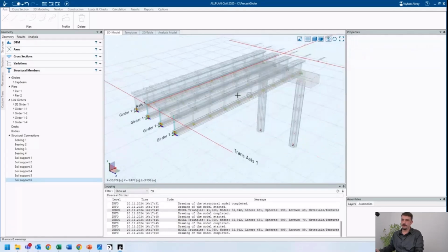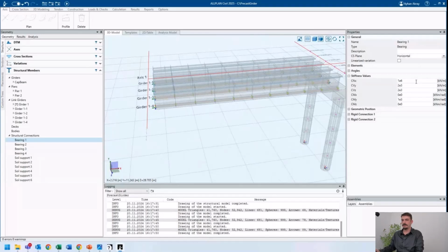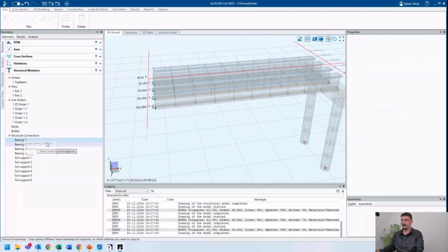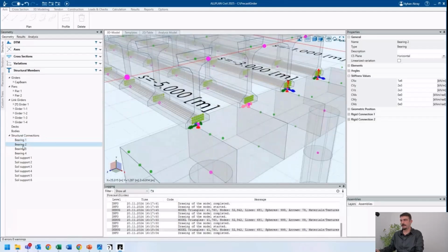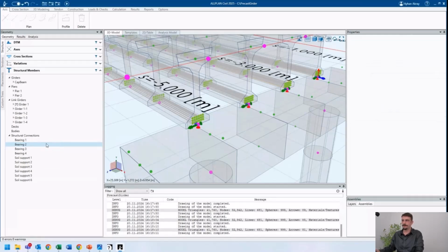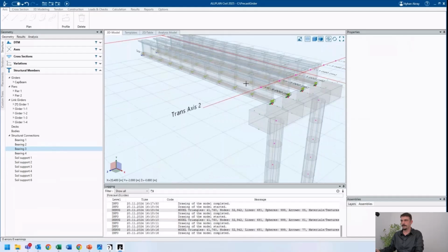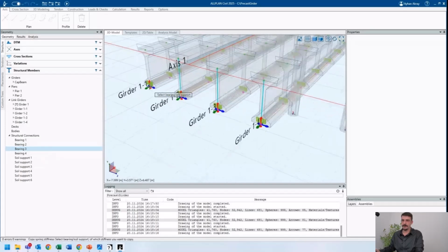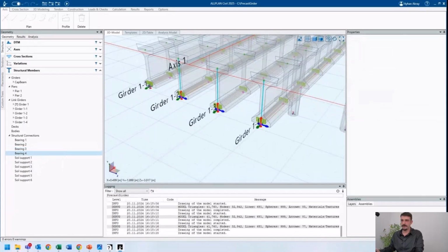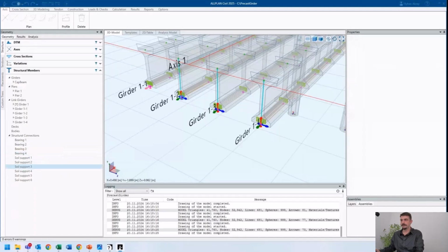In order to copy the rigidities, we can right click and copy our stiffnesses to the new function, so that I copy it to the bearing tool, you will see these have the same stiffness values. And we can copy this quickly like this. And from bearings to soil supports as well, because these have the same spring stiffness. I couldn't choose.